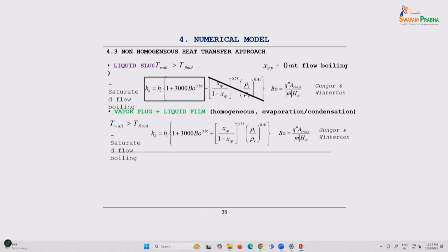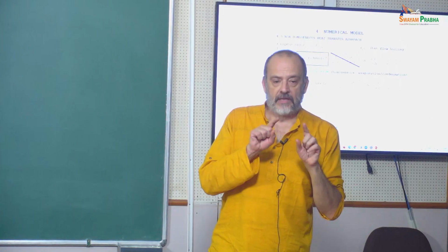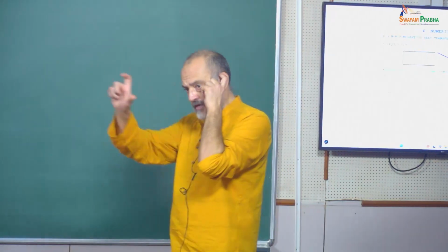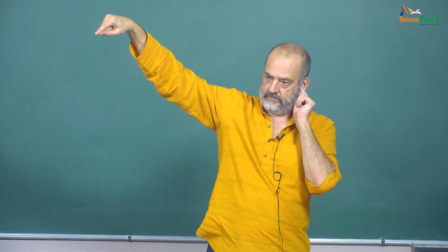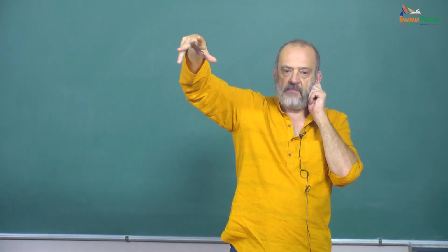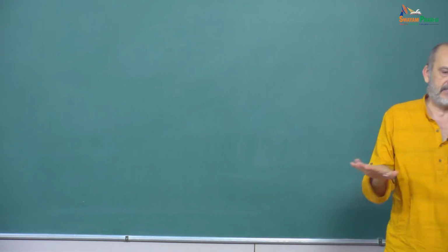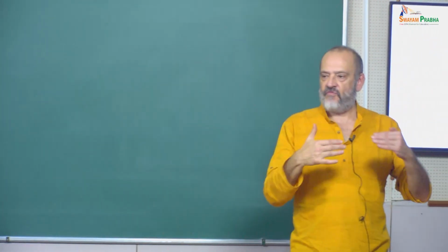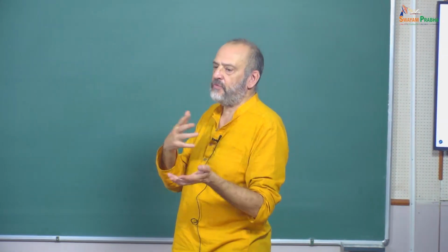In fact, we tried others, and this is very interesting, since one can say maybe this is not working. Look, the heat transfer coefficients on the boiling side and the condenser side are in any case very, very high with respect to the rest. Maybe it's not 10,000 W/m²K, maybe it's 15,000 or 20,000 W/m²K. We tried, and it doesn't change anything. The effect of a factor of 2 or 3 doesn't change the result in the end because the value is already very high.